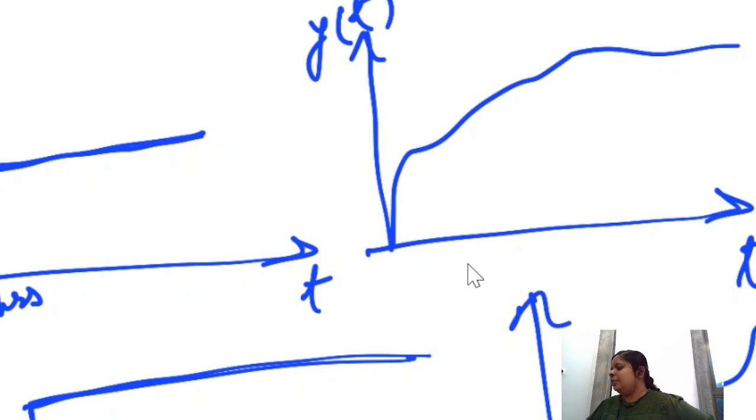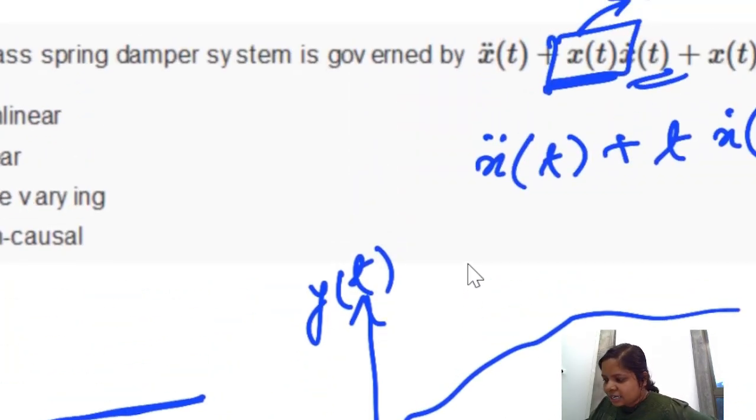Okay, then this means that this is a time invariant system. Time invariant system means that even if we change the time, say we do the experiment now, or 10 hours later, or 2 days later, if we give the same input we get the same output. Whereas if it is time varying, the result that you get now you would not get at some later point of time. So in this case there is no place where t is being explicitly used that would affect the result based on whether it happens now or later.